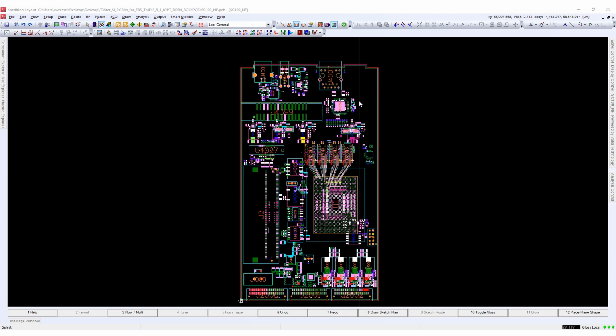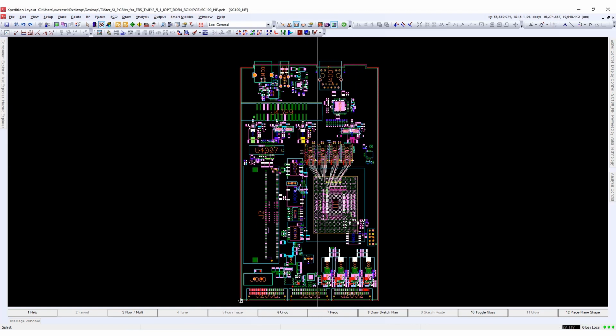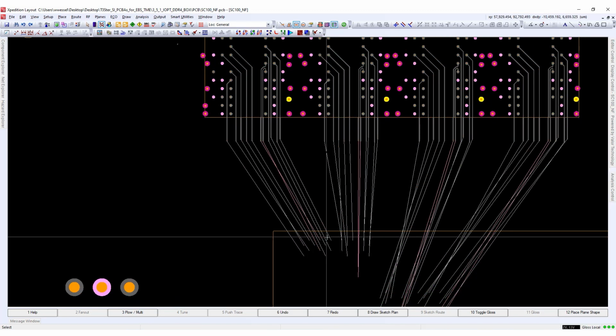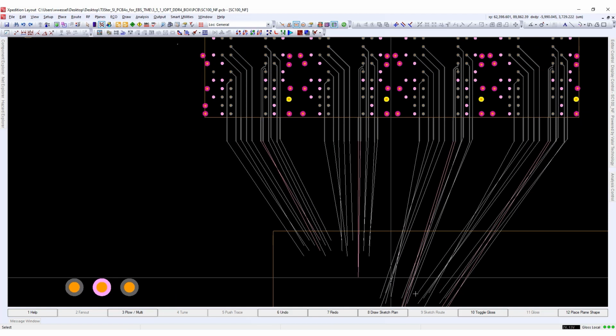We saw in the previous video that I/O optimizer is capable to guide during part placement and to support the fan-out and breakout process. In this phase of the design, we are using FPGA I/O optimization to improve the pin assignment based on the pre-routed signals, taking into account the layer usage. Before we can start the second optimization run, we need to use the methods and functions shown by Zach to complete the fan-out and breakout for all other signals.